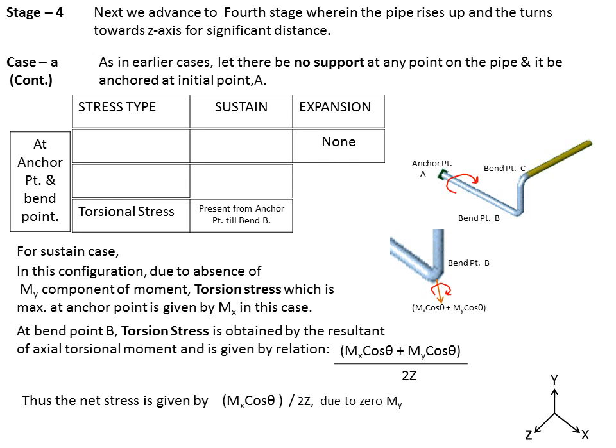Now again, looking at the expansion stresses, as there aren't any supports or any friction or any opposing restricting body which is going to restrict the thermal growth of this configuration, we won't be having any expansion stresses. So there won't be any axial stress, there won't be any bending stress, and there won't be any torsional stresses in the expansion condition for this configuration.